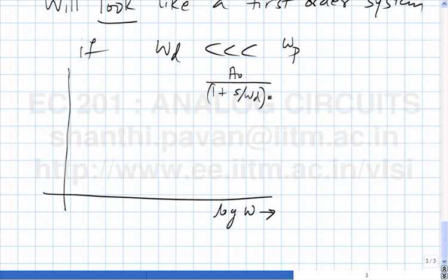We are dealing here with a large range of numbers. Omega d is much smaller than omega 1 and this A is a very large number hopefully. So, since we are dealing with large numbers, the picture will look better if I draw it on a log scale. So, if I plot log of magnitude of A of S, for very low frequencies, this is log A naught.